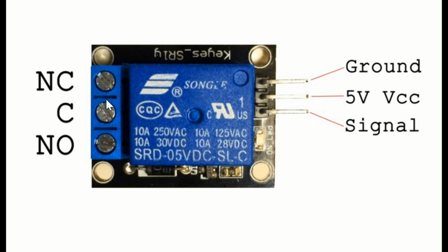So if we want, let's say, to control AC signals like AC lamps, fans, or bulbs, we usually use a relay. Why? Because on a relay, the primary side is low voltage, so you can't do anything with AC here. But on the output side, it's designed to handle AC signal.